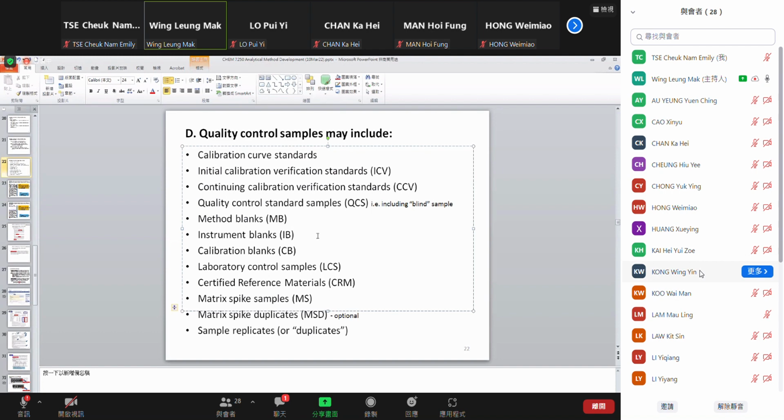For example, an overload, very high concentration in the previous injection, 1000 ppm. And your next analysis still has some of the target analyte. Maybe it is contaminated in the tubes, or inside the column, or even in the GC liner, and causes a false positive result.